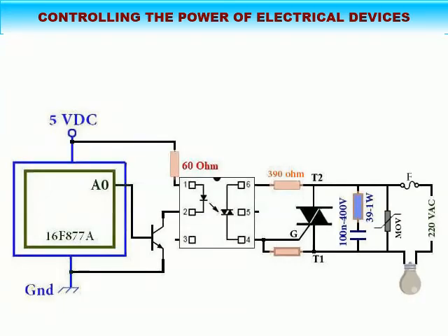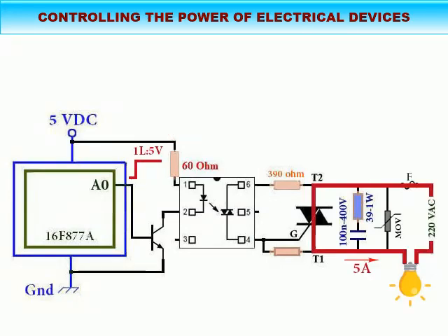As we mentioned earlier, the TRIAC is triggered by the microcontroller and the OPTOISOLATOR. The microcontroller issues the triggering command by sending a 1 from an output pin to the OPTOISOLATOR, which responds immediately and triggers the TRIAC. The OPTOISOLATOR, MOC3023, triggers the TRIAC randomly. That is, without knowing, or caring, at which point in the half wave the triggering occurred.